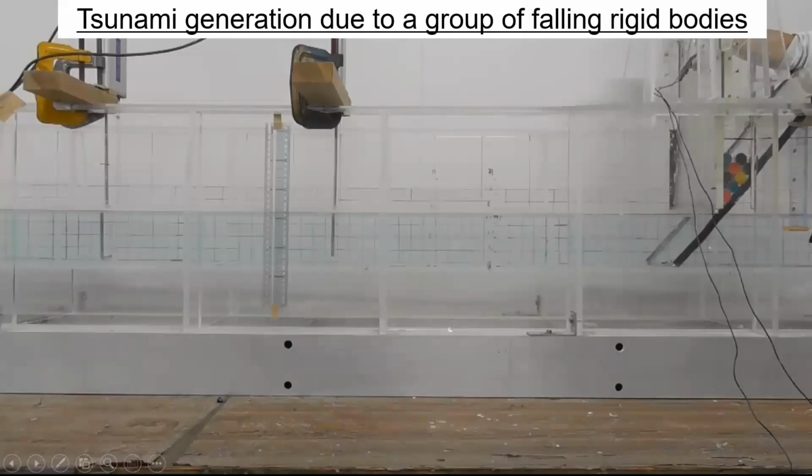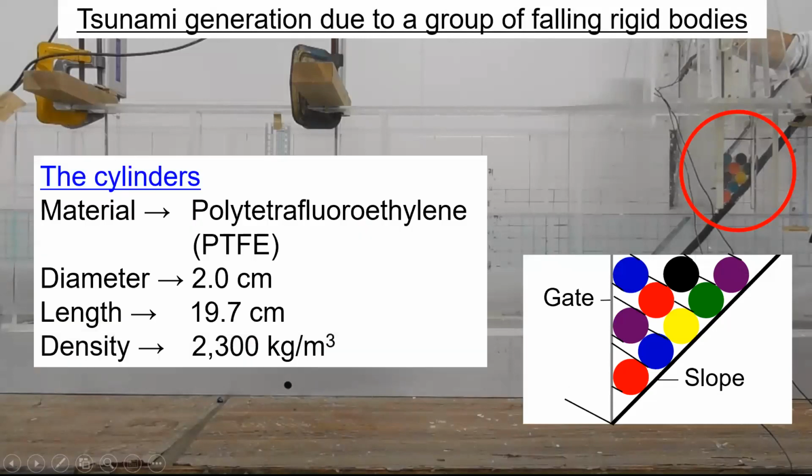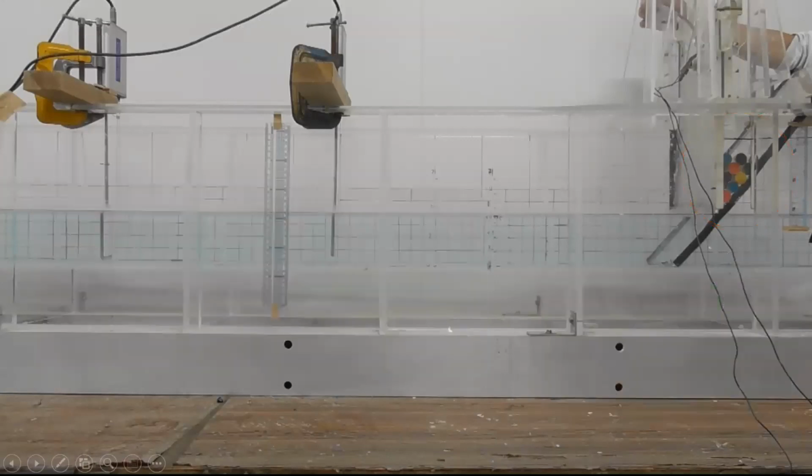In the second case, we studied tsunami generation due to a group of falling rigid bodies. We can see colorful rigid bodies loaded here. These are cylinders. The material is polytetrafluoroethylene, and the diameter is 2.0 centimeters. The length is close to the inner width of the basin. The density is around 2,300 kilograms per cubic meter.